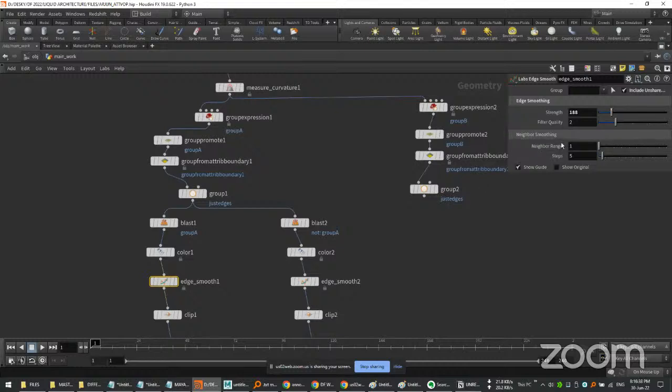What you want to do probably is increase the neighbor range by a lot, like 1,000 probably. And what will it do? It will smooth, but at the same time it will compress your geometry. So probably your geometry will change a little bit, but it will look smoother. Use like 1000, for example. I should change this to manual so that my laptop does not hang. My neighborhood range to 1000, and then again.